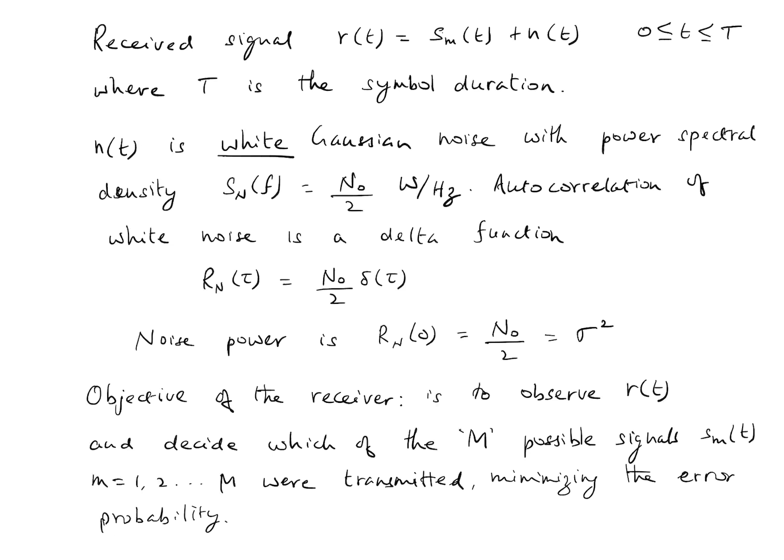And as we have seen in our earlier chapter on random processes, the power of a random signal can be obtained by evaluating the autocorrelation function at tau equal to 0. So when you put tau equal to 0, the answer that you get from the autocorrelation represents the noise power. And for a random process like the Gaussian process, which is also ergodic, the power is represented by its variance when the mean value is 0.